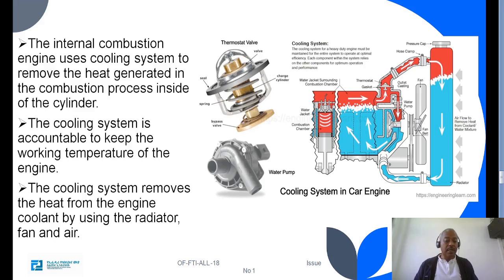So this is the cooling system in a car. The red color is the hot, and the blue color is the cold coolant. The coolant which leaves the engine is always hot, and when it passes through the radiator, the heat exchange takes place, and in the bottom part of the radiator we have cold coolant.